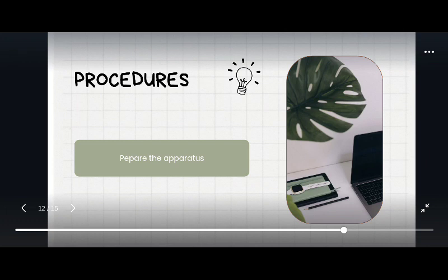Place the soil remaining in the cup onto the glass plate. Clean and dry the cup on the apparatus and the grooving tool. Remix the entire soil specimen on the glass plate. Add a small amount of distilled water to increase the water content so that the number of drops required to close the groove decreases. Repeat steps 6, 7, and 8 for at least 2 additional trials producing successively lower numbers of drops to close the groove.